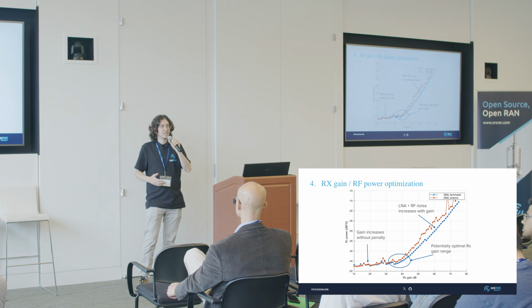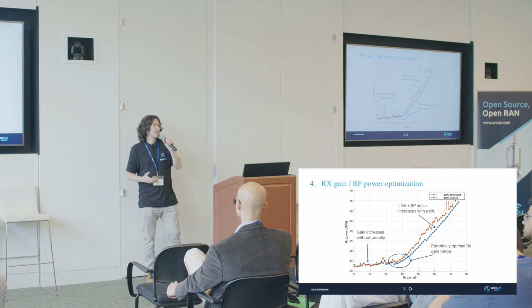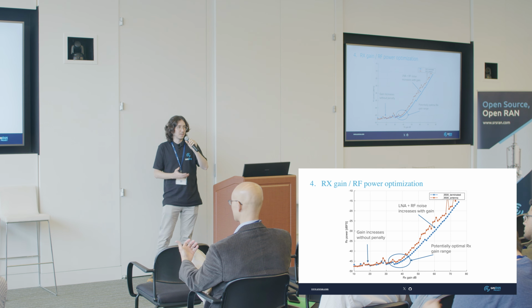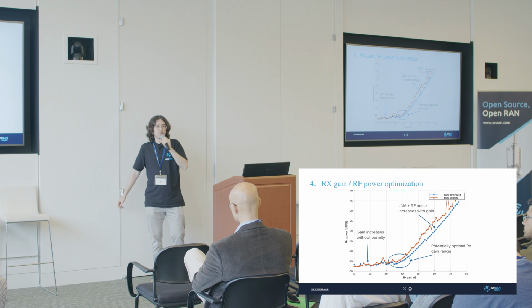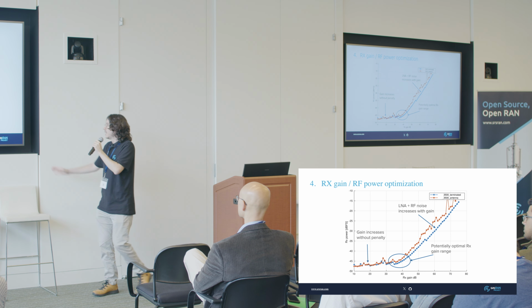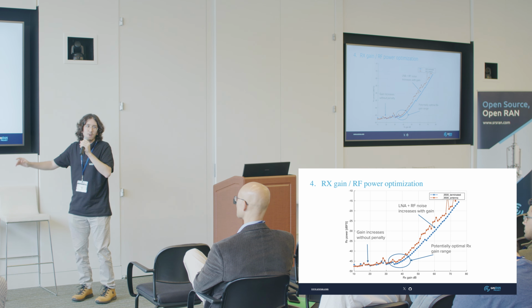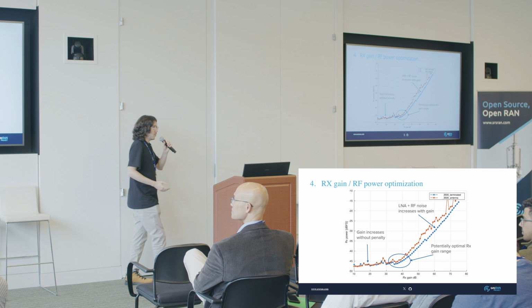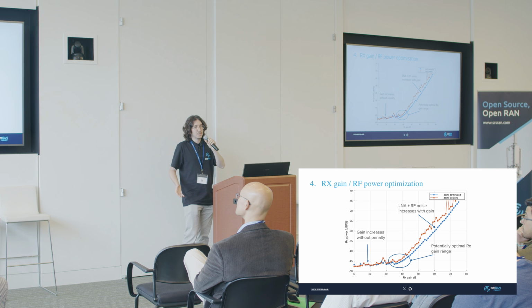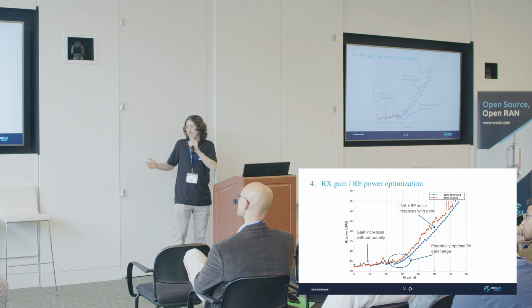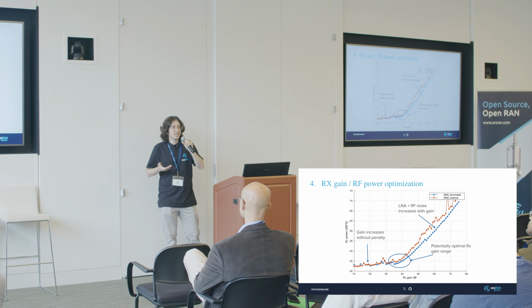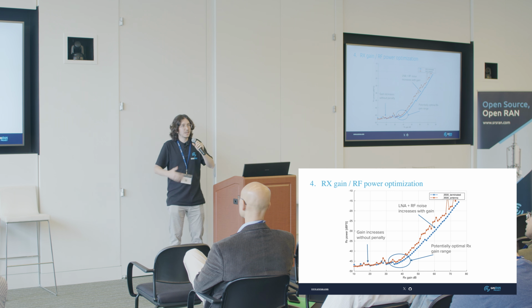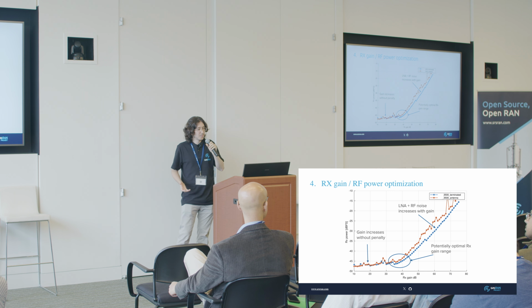So it looks like, in this case, the internal noise contributions are much more prominent, which is good for what I'm going to explain now. If the array receive gain is very low, in this situation the predominant noise source is the quantization noise, which means that if I increase the receive gain, the noise floor doesn't increase. This means that we can keep increasing free of any penalty.